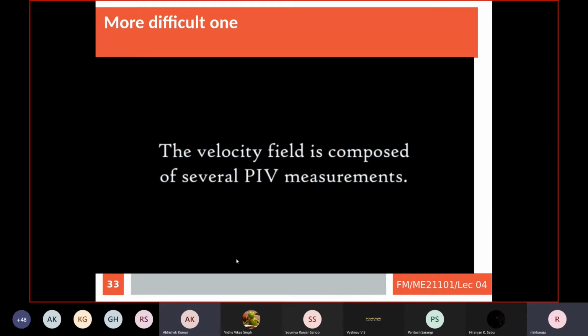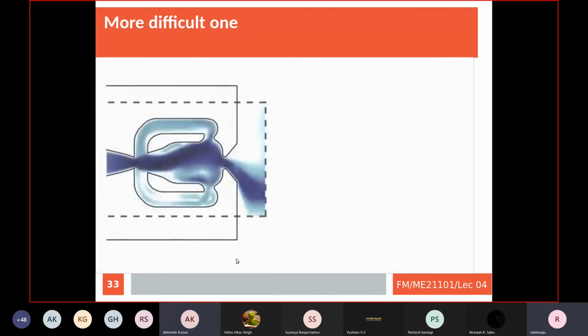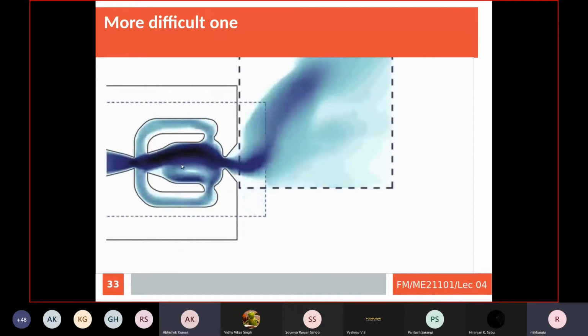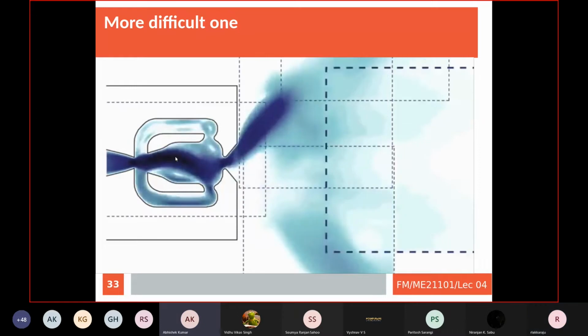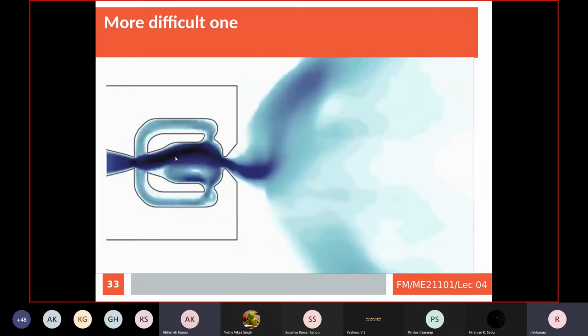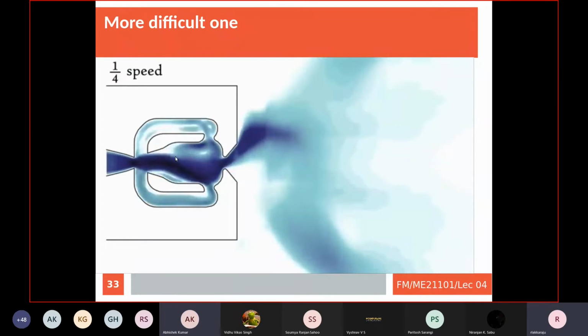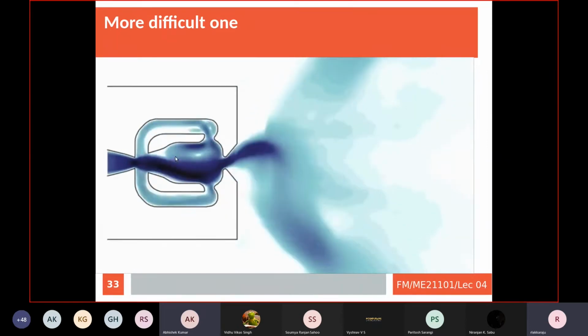This is what you call PIV, particle image velocimetry. So you sprinkle a lot of smoke or particles, tiny kind of things, and you visualize the flow. Now the colored one is dye. So it's supposed to be your streak lines. Now what they are trying to look at are different zones. Very slow speeds, how it really looks like, and so on.